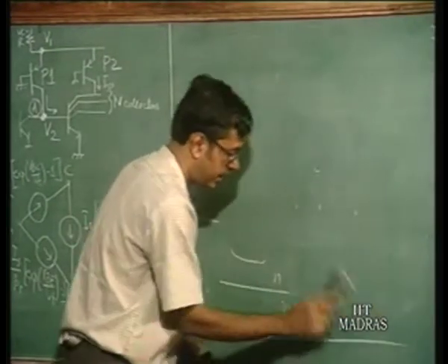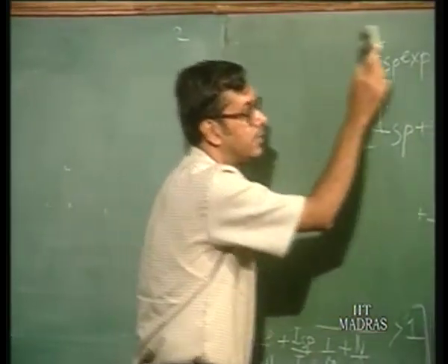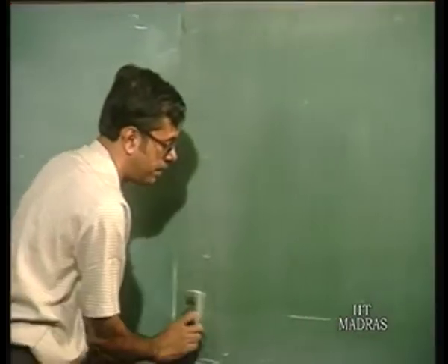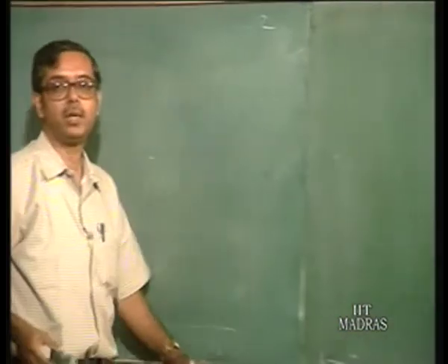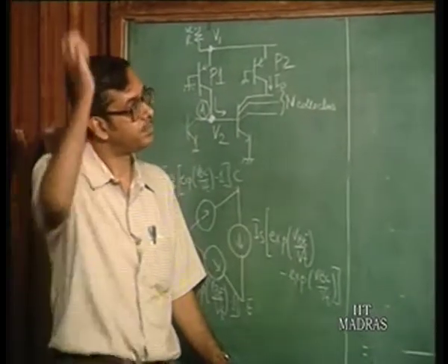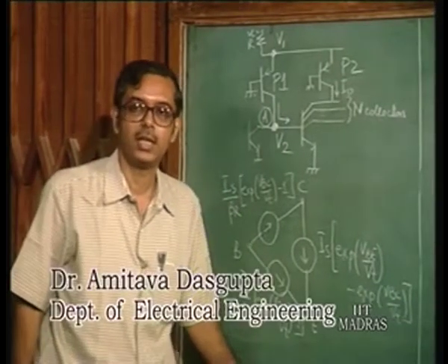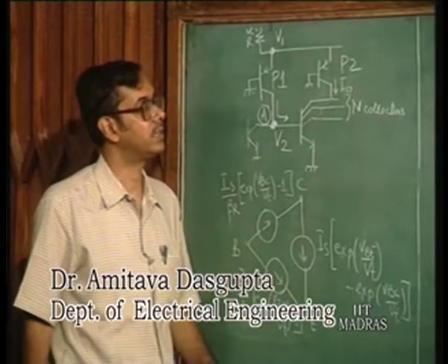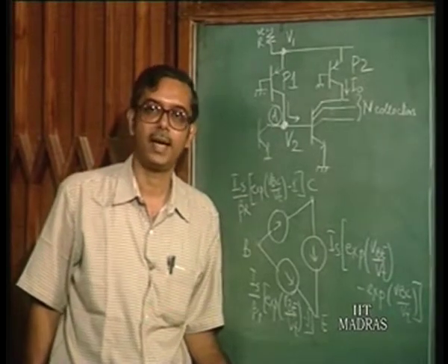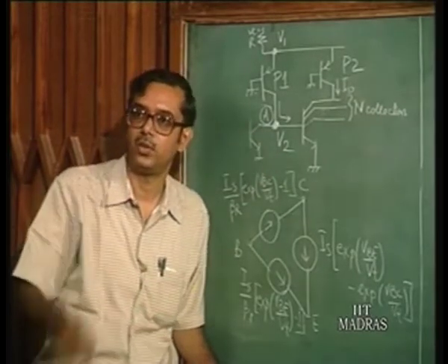So, we shall go ahead with our discussion now again, and the next topic which we shall look at is the different characteristics of the I squared L cell as such, that is the noise margin and propagation delays, by which you characterize a particular logic family. Okay. All right. Now, firstly, if we take up the noise margin, that is quite obvious also that the noise margin in a I squared L cell is not going to be too good, because of the fact that the voltage levels are constrained to within 0.2 to 0.7 volts at each node.